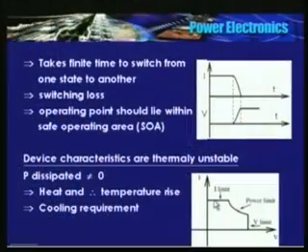So it cannot pass 75 amperes at 1200 volts, it's just not possible. So there is a limit. The voltage across it could be 1200 volts, but then current should be within this limit. See, this is the limit, and this is the power limit.